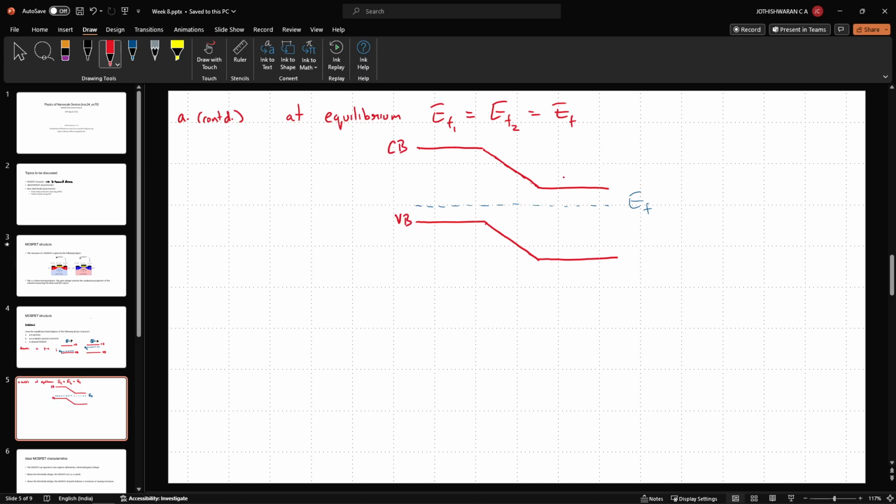So now this is the conduction band and this is the valence band. And this is region 1, this is region 2. Now we have a third region in this system which corresponds to the junction. Essentially, when we have a PN junction brought together, we'll form a depletion region in the junction where there are no free charge carriers. So this energy barrier indicates the absence of free charge carriers. So we have an electron rich region over here, we have a hole rich region over here, and in the middle we have a depletion region.